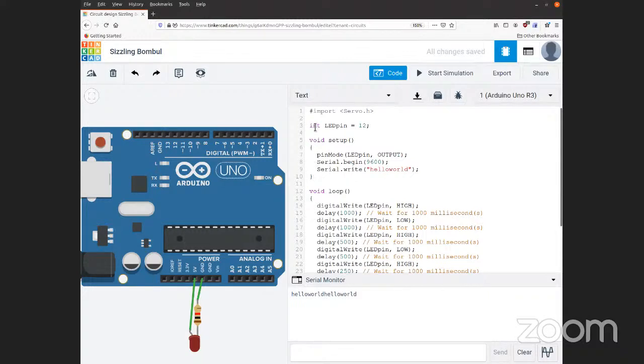What does Serial.begin(9600) mean? So let's just dissect this single statement even further. Serial means that you're talking about the serial connection, and .begin will initiate a connection, which is a protocol in serial communication. And finally, you might be wondering about this 9600 number.